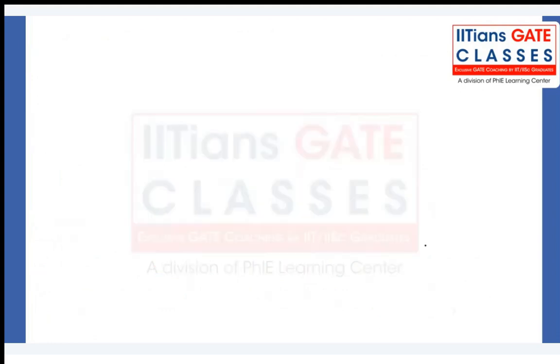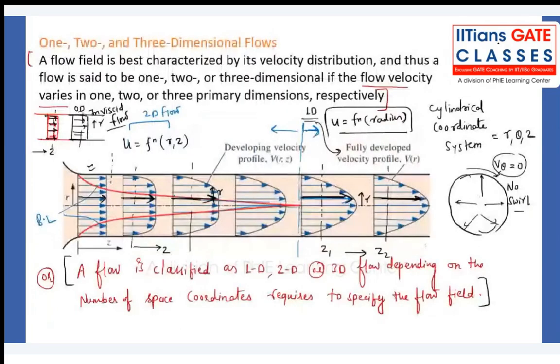As of now, based on the cylindrical coordinate system, when the fluid velocity varies in the r direction, theta direction, and z direction, then we say it is a 3D flow. But in the pipe flow problem with boundary layer formation, v theta will be zero. There is no angular velocity, right? The fluid is not flowing like this. The fluid flows in the z direction, right?